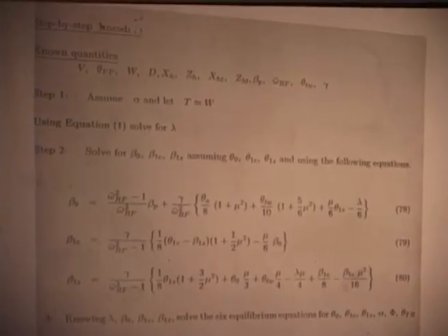Then blade response depends on what type of model you are having for the blade. Okay. Here we have included only flap, please understand, in a real helicopter you have to have flap, lag, torsion, all must be included, okay, and it will be much more complex. I will show those results a little bit later.